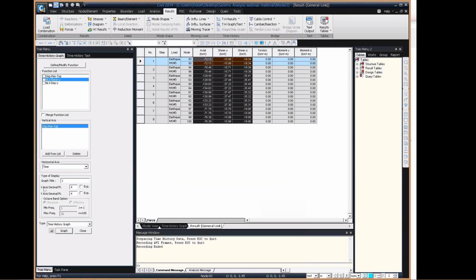So the overall purpose of time history analysis is not essentially to design the structure, but rather to observe its response in a realistic earthquake setting. So the structural design is more or less completed from the response spectrum and the pushover analysis considerations. The time history considerations generally act as a checking measure for observing whether or not the structure is safe.